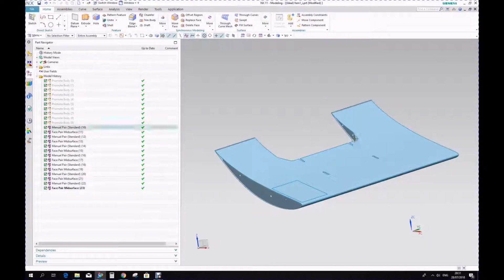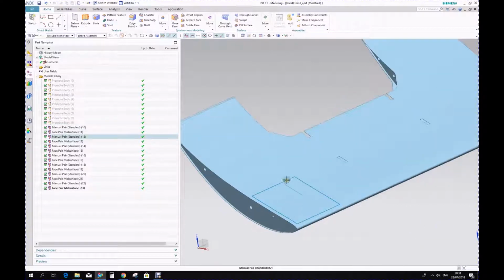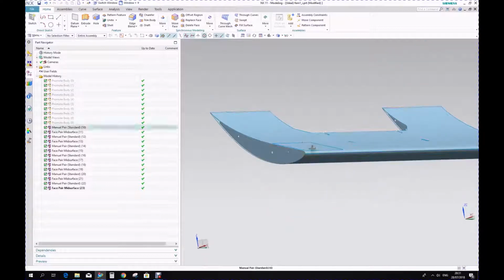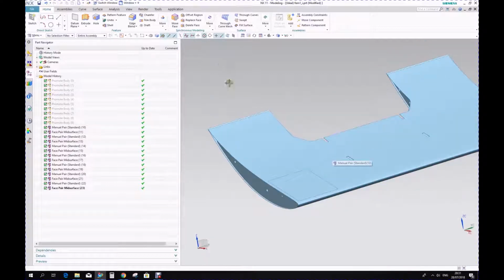So what we want to do is sew the bodies that should be connected with each other. For example, to fix this top main plane, we need to sew this edge and make these two bodies a single body. Otherwise you're going to apply the load on this square and it's not going to transfer to the rest of the part, of course.